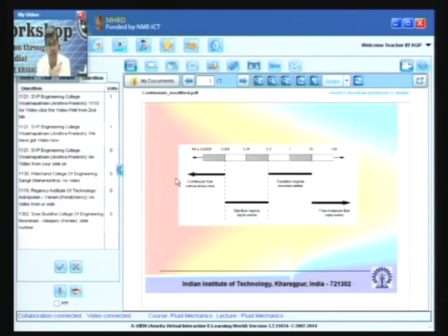Again I am telling, the tangential velocity, or velocity along the solid surface, of a fluid with respect to the solid surface becomes 0. That is the no slip condition, and this is a consequence of the interplay between the solid and the fluid by the force of attraction or adhesion forces between the solid molecules and the fluid molecules, where the no slip condition will be valid.